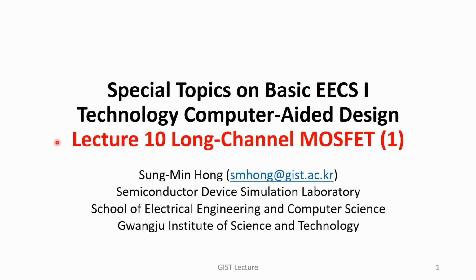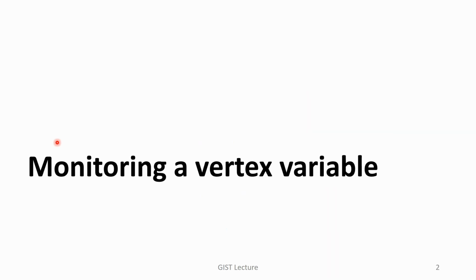Hi everyone. From this lecture 10, we simulate a long channel MOSFET. Today, a MOSFET structure is generated and the equilibrium solution is obtained. Before starting today's lecture, a way to monitor a vertex variable is presented. In other words, now your CSV file can have extracted vertex variables.